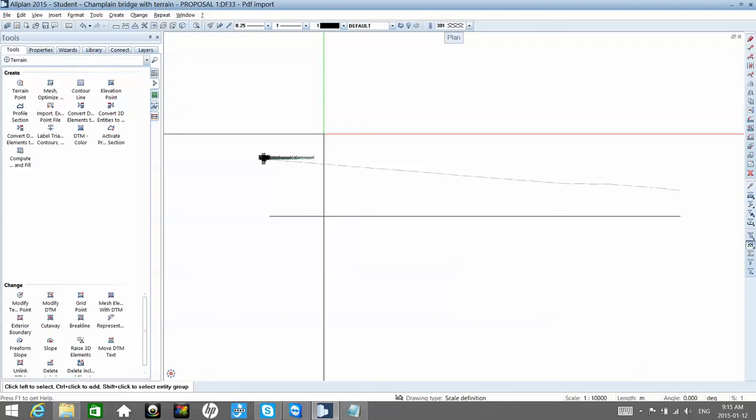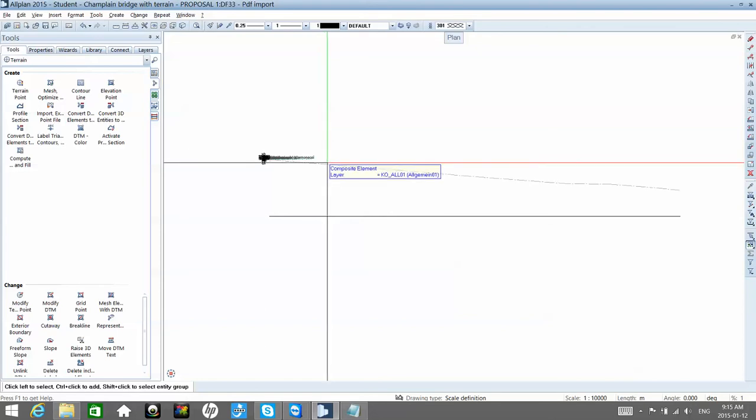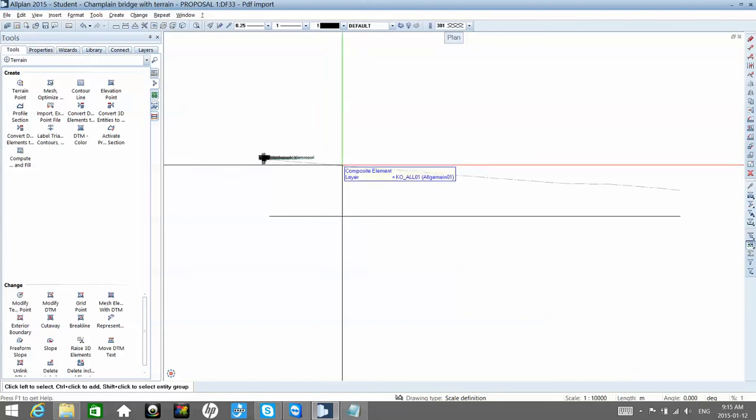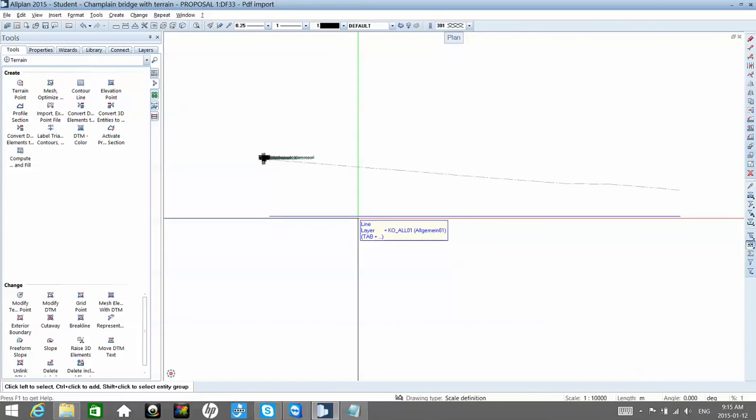However, the software with this module, the bridge and tunnel function, needs two lines. One is the variation in plane, which is this one you drew, and the other is a variation in elevation, which is the second line. Combining the two lines together, by combining the two profiles, we obtain a 3D line and the bridge.